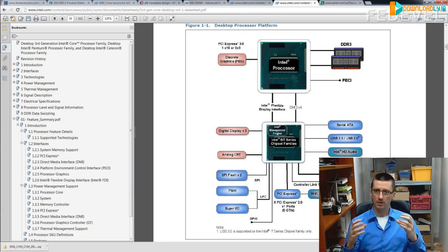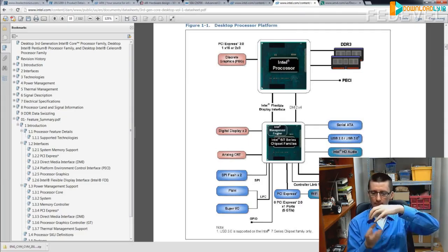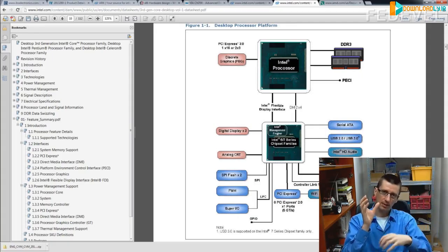What it means, if you have a CPU hungry application, so you know you have one heatsink, you have one power dissipation from the chip, maximum power dissipation, and if graphic doesn't work on full power, processor can actually work on little bit more power, and when processor doesn't work on full power, graphic can work on full power.